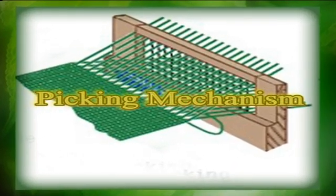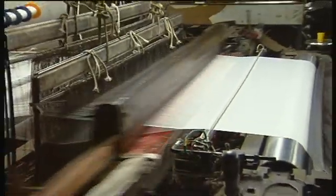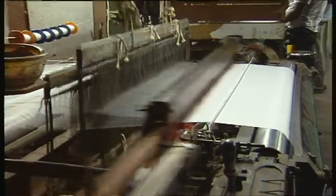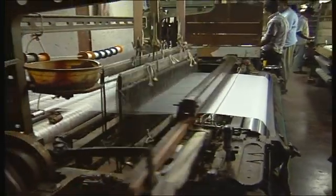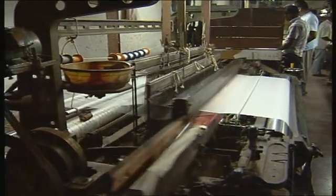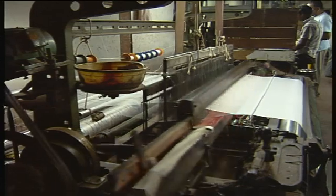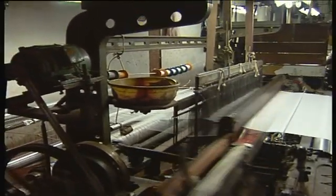Coming to the picking mechanism, passing of the weft thread from one side to another through the division of warp threads is known as picking. It is done by giving a lateral motion to the picking handle and thereby driving the shuttle across the shed.